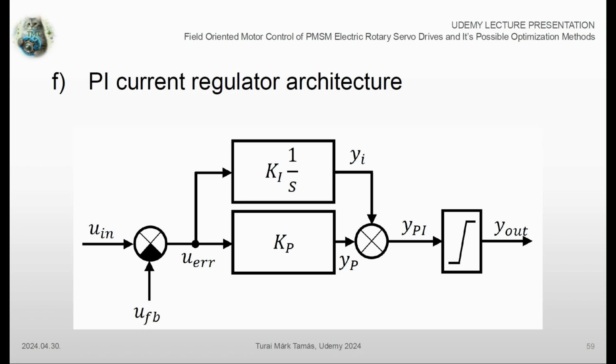Afterwards, saturation limitations shall be included in the implementation as well to ensure that the controlled physical quantity stays within the boundaries that the system defines. For example, the direct and quadrature controller's outputs are the voltage signals interpreted in the relevant directions. Our model system is going to have a certain voltage level supply either from a battery or from a power network.